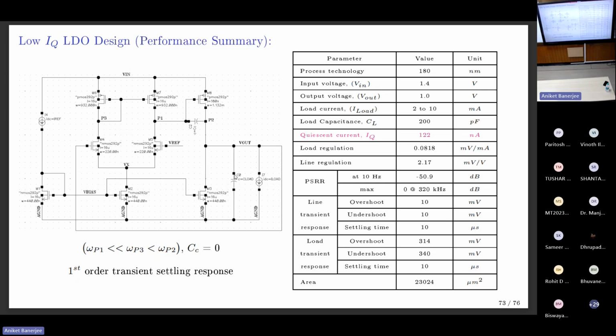Yes, you reduce the current in the last step, so that you bring the W parameter with respect to L so that W by L was less than 1. So can we reduce the current so as to bring the design into that sub-threshold region? I mean, can the same procedure be followed with the sub-threshold design also, or will there be some alterations?